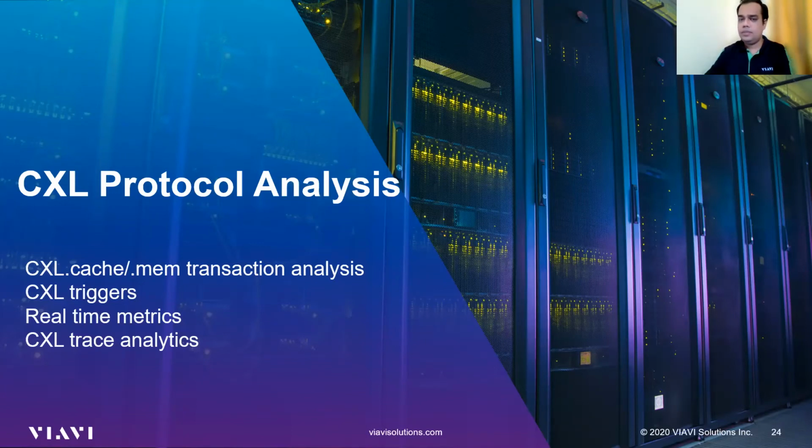So from here, we will move to the CXL protocol analysis. We will cover CXL cache memory transaction analysis, CXL triggers, some real-time metrics, and CXL trace analytics using the Xgig protocol analyzer.